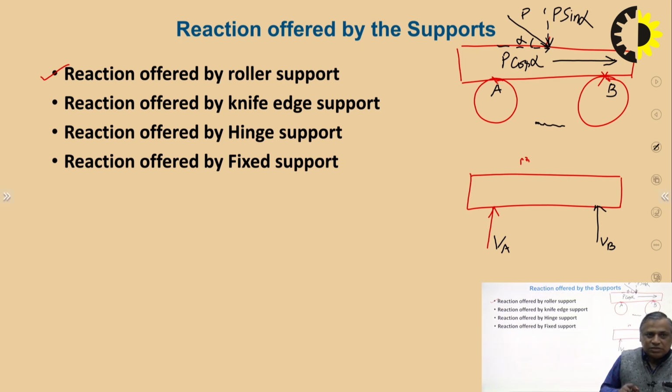So, in our syllabus for this course, we are only dealing with the statically determinate beams. That's why I mentioned this line. One support should be roller or knife edge and the other must be hinge, so that the hinge can resist the horizontal movement of the beam. The beam should not leave the supports, otherwise the purpose will be lost.